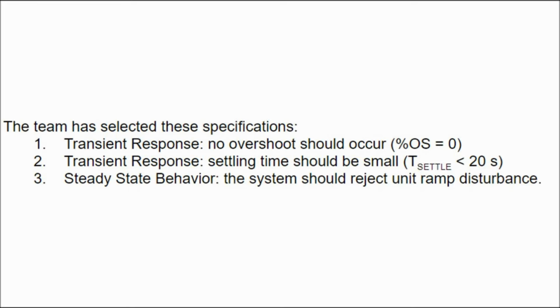For the initial design of our system, the following criteria were chosen. Through transient response design, we chose an ideal 0% overshoot. This accounted for height oscillations that needed to be dampened in order to reduce risk for collisions while descending. We chose a settling time of less than 20 seconds. In the interest of time and efficiency, these drones would need to drop off packages relatively quickly.